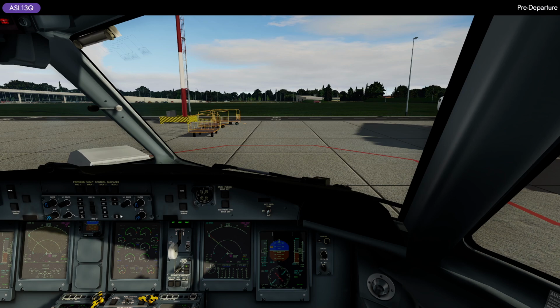This means we take off with takeoff power. At 800 feet above ground level, we reduce power to the climb power. And we continue the climb in the takeoff configuration to at least 3000 feet above airport elevation. And that is the moment where we can actually increase speed to the clean speed and do the retraction of the flaps and everything else and do the acceleration.